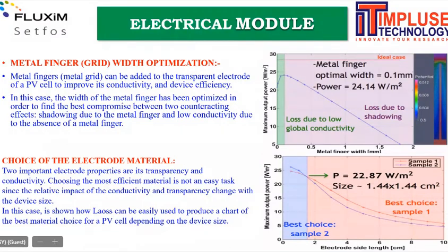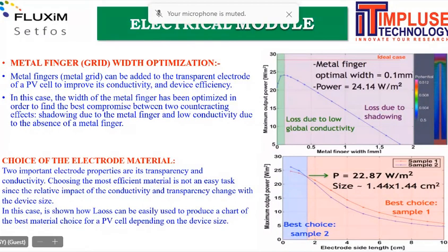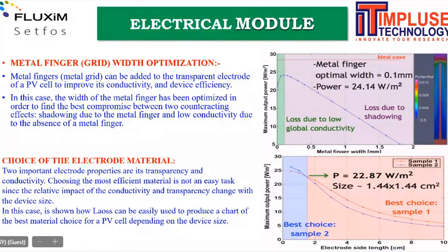You can optimize with a minimum value and maximum value, and run the job. You can set the minimum and maximum of a particular parameter, let's suppose temperature, potential, thickness, or current, and run the job. It will plot the characteristics at each and every point, voltage or whatever input you have given.